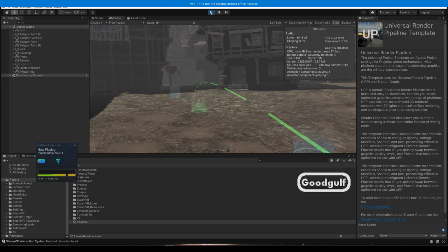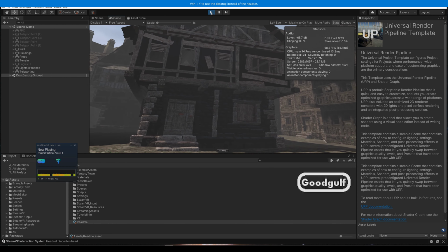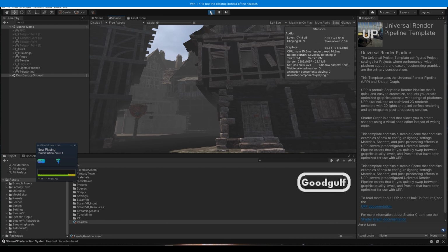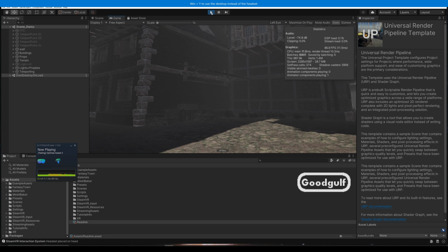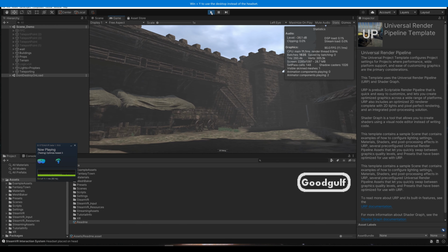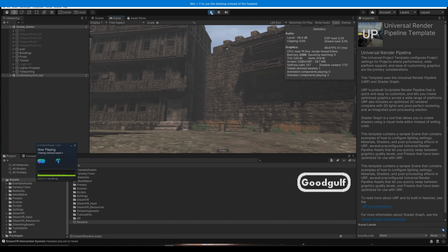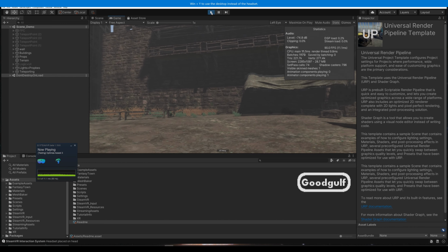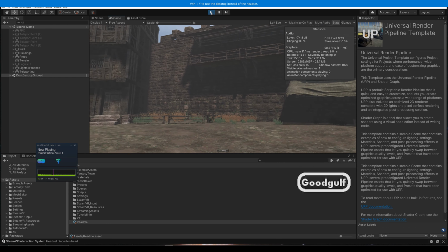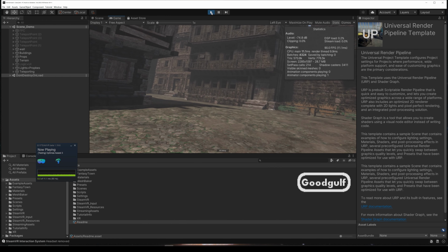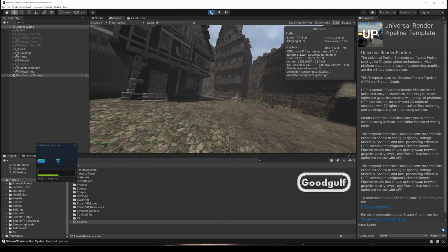This time I will be trying to get an asset working which has not been optimized for VR. I can tell you upfront, this has been a lengthy process and it's still far from perfect, in a sense. Why? Well, because there seems to be an easy way out there. Just convert your project into a URP and an immediate jump up in frame rates is visible. For the asset I picked, it went into the green zone with a few simple changes.